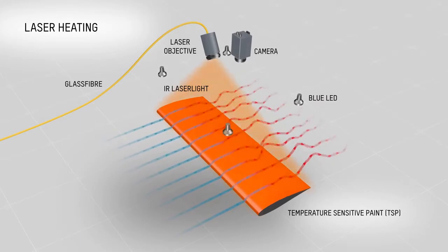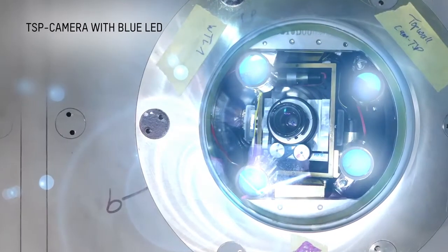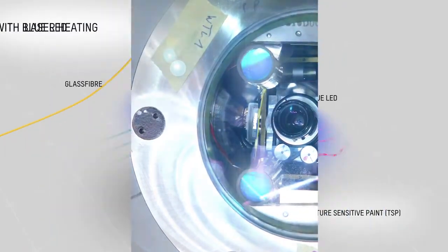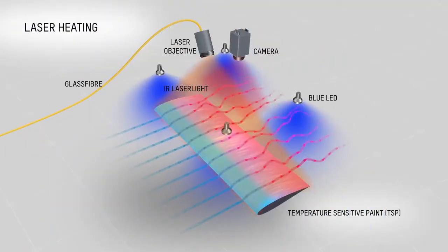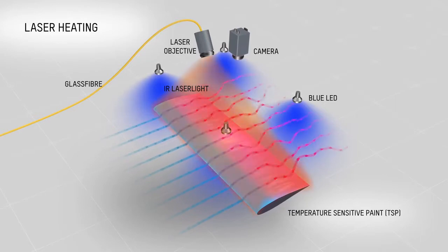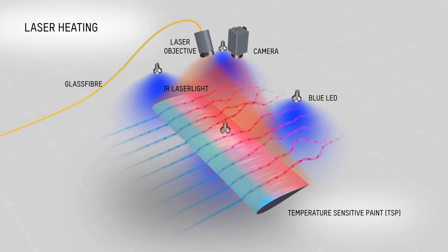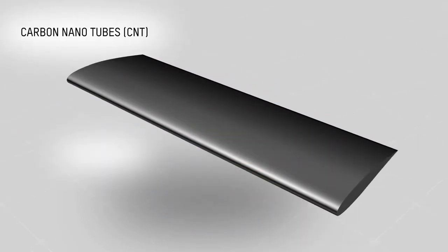The active TSP molecules on the surface are excited by a blue LED light and in return emit a red light. The major advantage of the laser-based concept is that the high-energy infrared laser light is transferred via a glass fiber into the cold and pressurized wind tunnel.